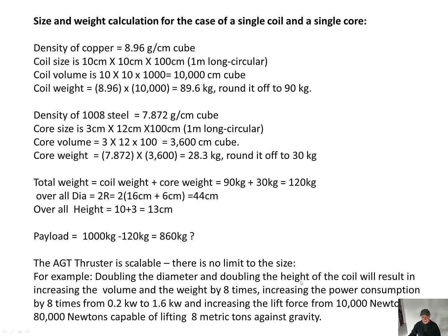There is no limit to the size. For example, doubling the diameter and doubling the height of the coil will result in increasing the volume and weight by 8 times, increasing the power consumption by 8 times from 0.2 kilowatts to 1.6 kilowatts, and increasing the lift force from 10,000 newtons to 80,000 newtons, capable of lifting 8 metric tons against gravity. So there's no limit, it's scalable.